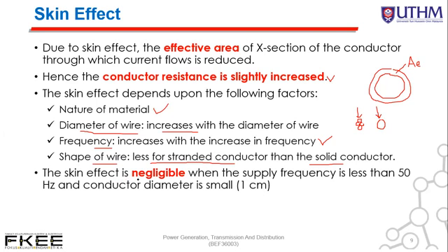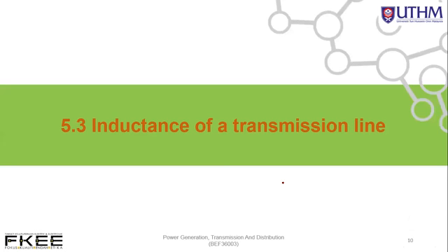And the skin effect is negligible when the supply frequency is less than 50 Hz and the conductor diameter is small, that is less than 1 cm. Okay. Now we look at the case of inductance of a transmission line.